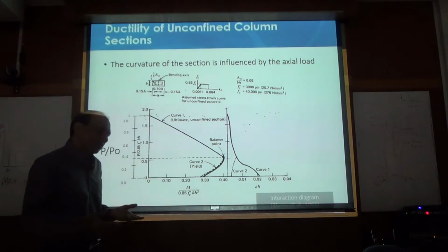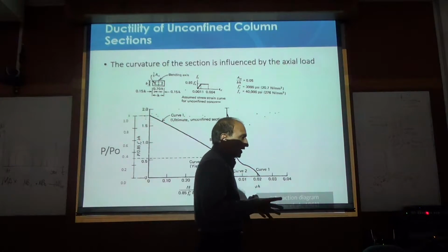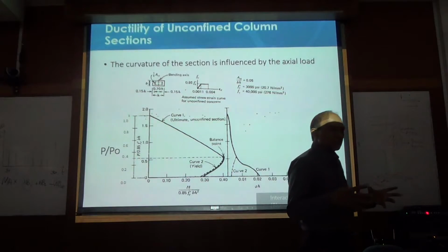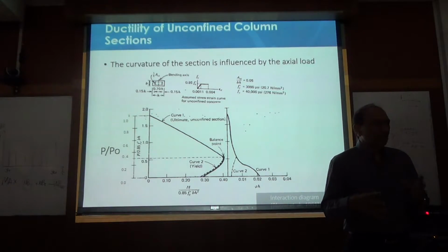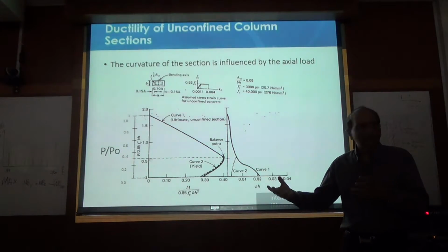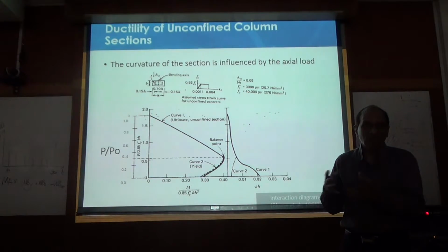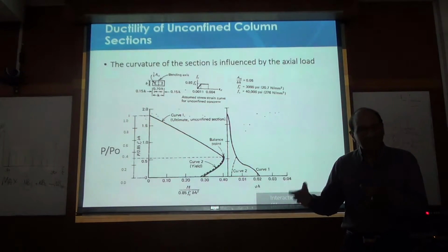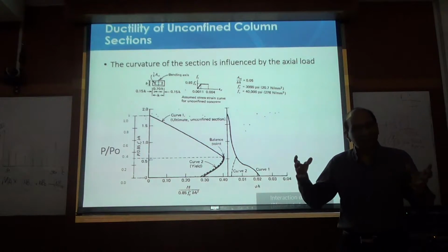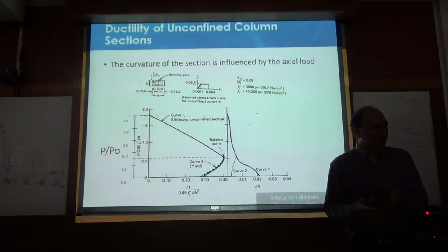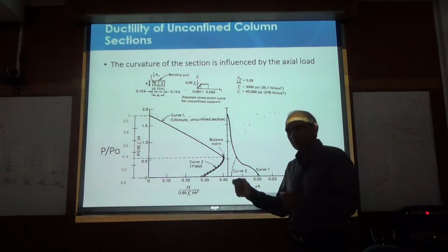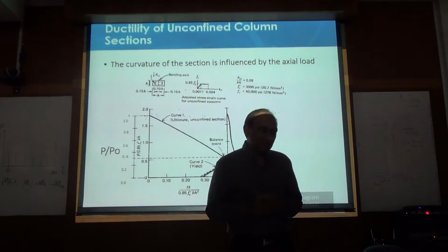But that's a problem because the architects and clients want the column to be as small as possible. So what we want and what the client and the architect want is totally opposite. We want columns with low reinforcement, low concrete strength, large size. They want the smallest column with the highest concrete strength with a lot of reinforcement, right? So we are always in trouble with that.